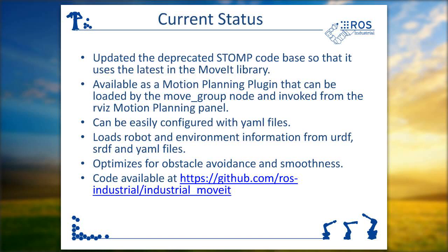So what's the current status of STOMP? We managed to upgrade the source code of STOMP so that it uses the latest in the MoveIt library, or at least what's in Indigo at the moment. We've also managed to make it into a motion planning plugin, which can be loaded by the Move Group node, and that allows STOMP to be invoked from the motion planning panel. So you can essentially call STOMP the same way you would call any of the OMPL planners that are currently available to MoveIt.